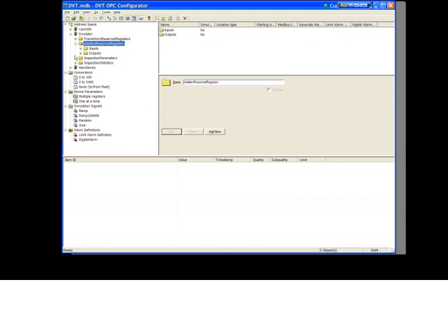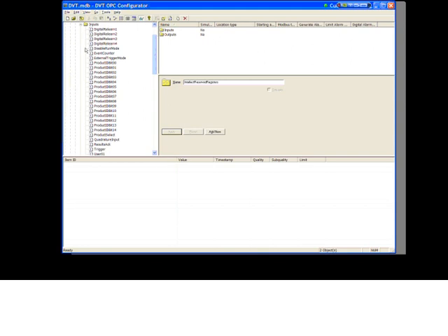But most of the time, besides the I/O, which is very helpful, for example, you can trigger a camera through OPC. You can relearn different models for different tools or colors for color tools, etc. Anything that can be relearned through a digital relearn signal, you can do it as well here, because again, you have access to the entire virtual I/O map. So this is very, very useful indeed.